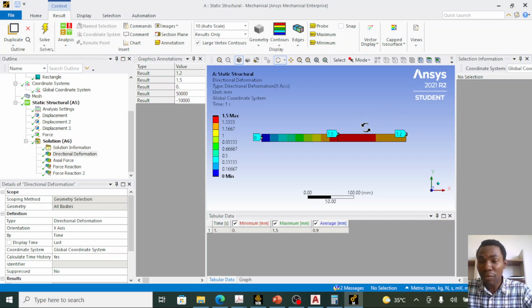The overall effect of the 40 kilonewton force and the 1.2 mm deformation at node 3 is to cause stress in the first finite element, however, there won't be any stress in the second finite element, because the 1.2 mm deformation is placed at node 3, and also 40 kilonewton, which is equivalent to 1.2 mm, is placed at node 2. So they move together, causing zero stress in finite element 2. The stress in finite element 2 is caused by the remaining 20 kilonewton force. So it's the remaining 20 kilonewton force that actually stresses finite element 2 and finite element 1. So this is the explanation of the boundary condition, and why I apply the boundary condition in this manner in the ANSYS program.